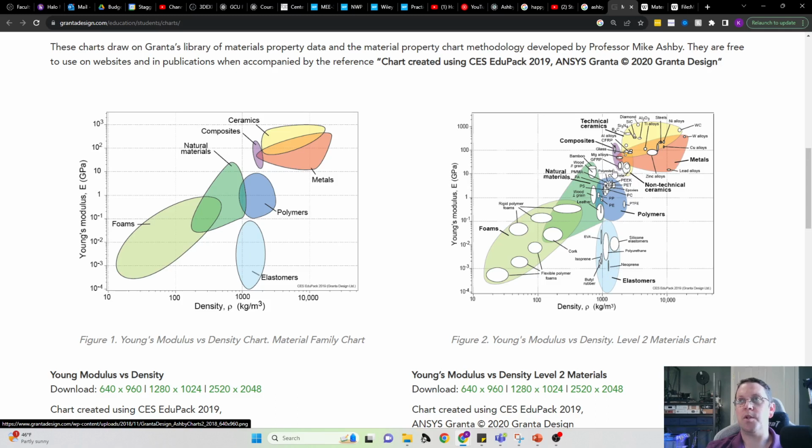Should tell you why we build a lot of stuff in concrete. There's also some really interesting composites. So carbon fiber reinforced polymers versus glass reinforced polymers. Carbon fiber reinforced are much stiffer. Magnesium alloys, much lower in density, but also lower in overall stiffness compared to tungsten or even copper, interestingly enough.